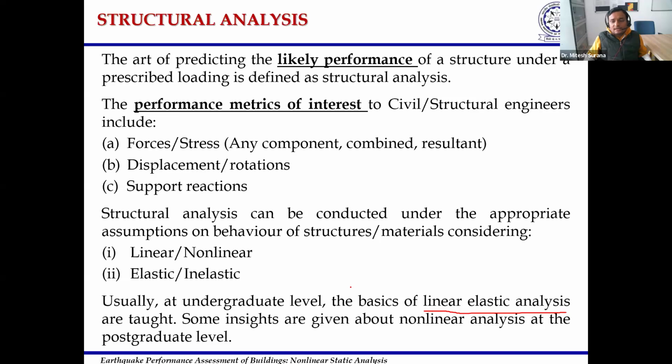However, we will see that in case of earthquakes, the assumption of linear elastic behavior is not true, and we need to understand non-linear analysis. So this is why we need to understand non-linear static analysis particularly, because this forms the background to understand how the structure actually behaves during an earthquake and how we can determine its actual response. Therefore it becomes essential to know first the linear elastic analysis, and then we can proceed to non-linear analysis. So I am assuming that all the participants have enough background on linear elastic analysis, and I will mostly focus in this presentation on non-linear analysis.